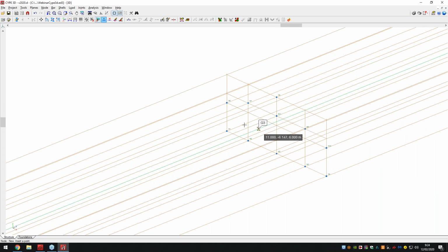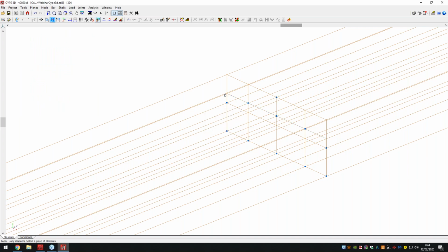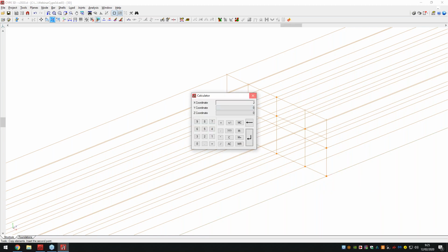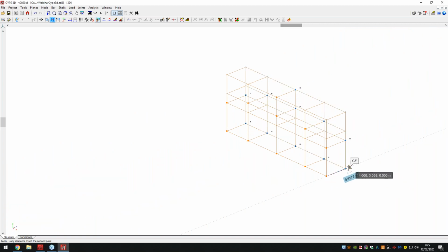So I've created those 3 nodes here. What I can do as well, of course, with the capabilities is copy my elements. So I can, again, come over here, select the nodes that I want to copy, right click, select my given starting point, and I can move in particular directions to copy that node. So I can just move over, let's say about there. Let's say 2.5 meters spacing. And you can see here, the program will insert that for me. And here you can see I'm building a sort of family of nodes.